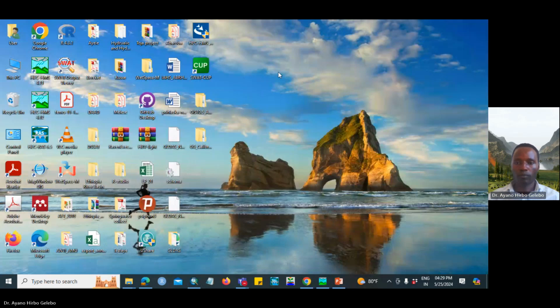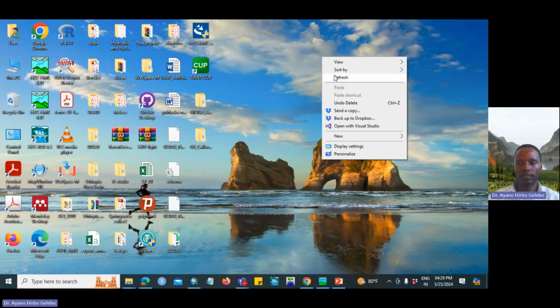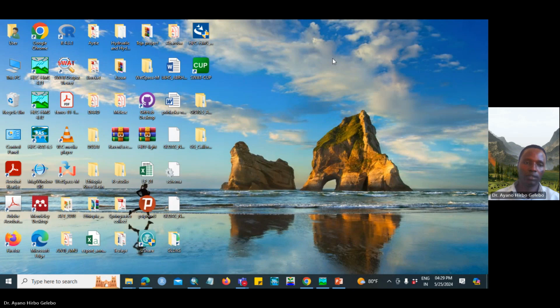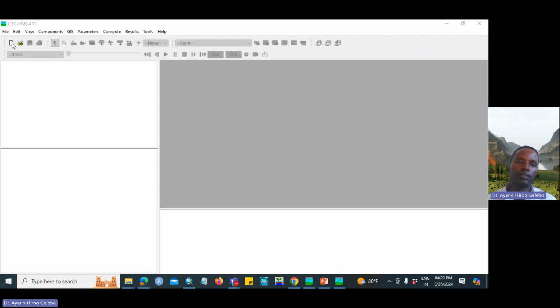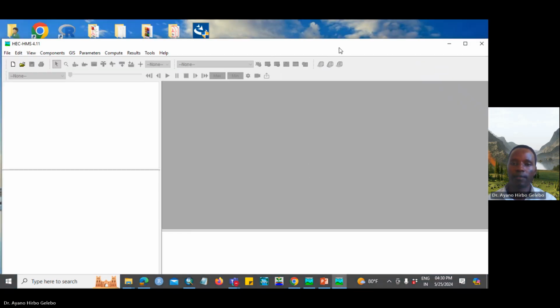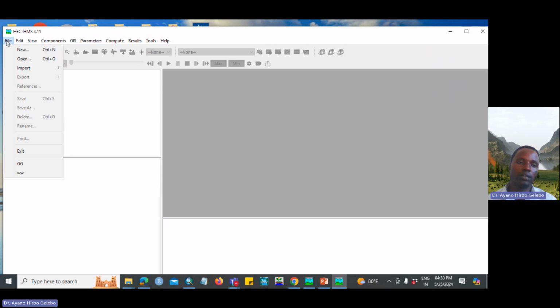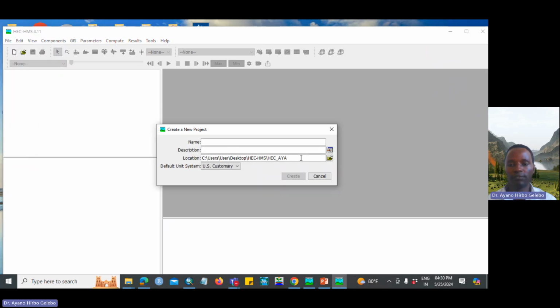Now I'm going to give the training. This is HEC-HMS 4.11. Open it and click on it, and let it load. This screen will come up for you. Then click on File, then create a new project. You can give a file name.